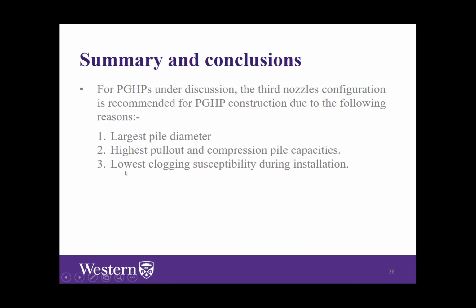Also, the nozzles looking upward decrease the possibility of getting blocked during installation. For the second nozzle configuration, when your nozzles are looking downward, we sometimes observed nozzle clogging and the grouting process can't be performed. So the third configuration has much lower clogging susceptibility.